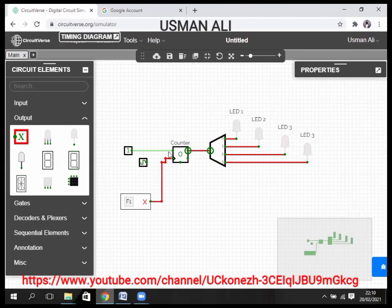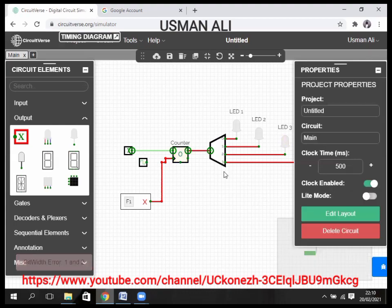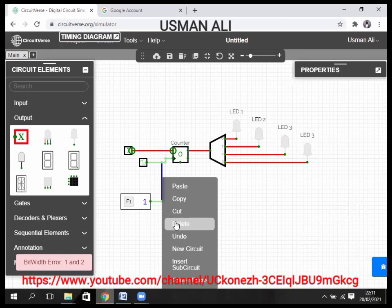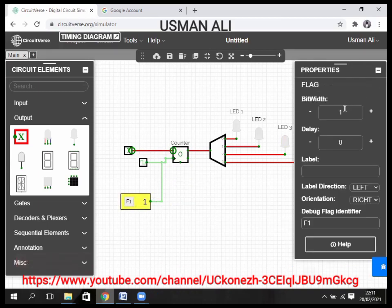Now you have to change the bit width of the counter here and put it to 2. Now you see it's not 1, now it's 2. Then connect the clock. Here you see the bit width of our flag is also 1. Therefore, we disconnect it. First, we connect it, point it, and the bit width is 2.